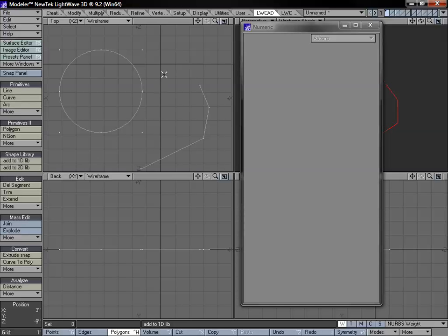Our next tool we're going to take a look at is basically the same thing, except the fact that it's not going to give us a curve, and that's the Chamfer Tool. So we'll select, I'm going to start out with our top line, and then our bottom. And now you can see we basically have the same thing, but now we have a direct beveled edge. We're just using 2 points and one line to connect these two, and we can adjust our distance as opposed to our radius now. So that's fairly straightforward.